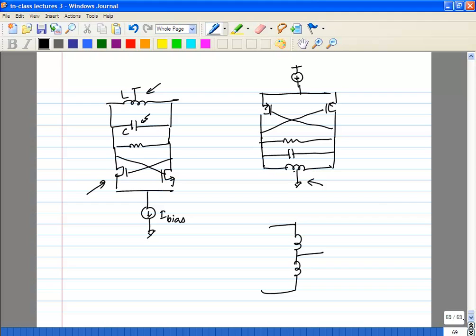The resistance is obviously not what you add, it stands for the losses in the tank, and usually the losses in the inductor dominate because remember that you have a series resistance, that times Q is your parallel resistance, right? Typically the Q of the inductor would be like we have seen, 8 or 9, 10 maybe maximum.